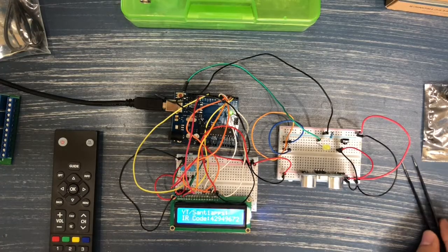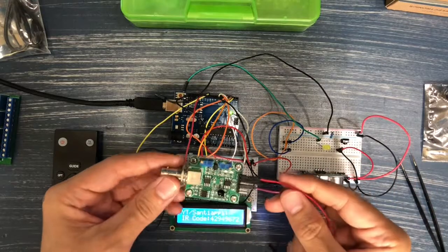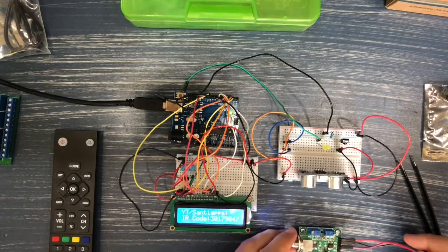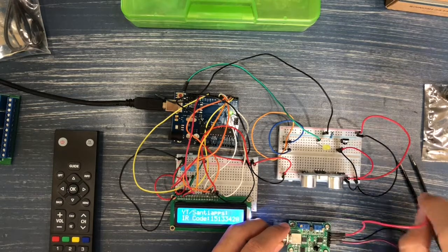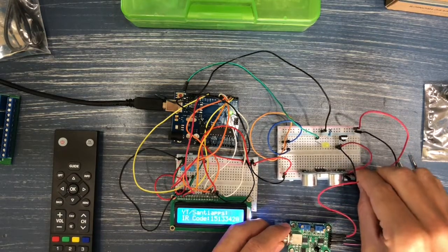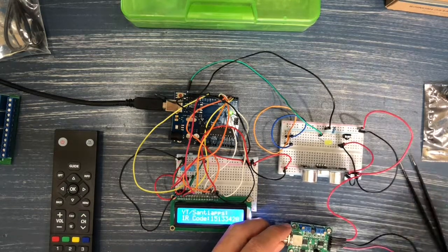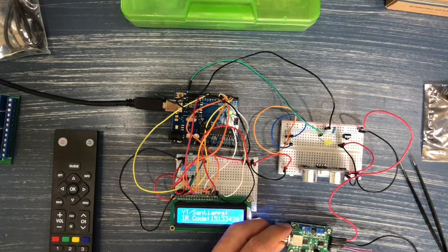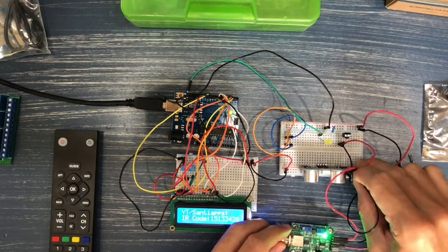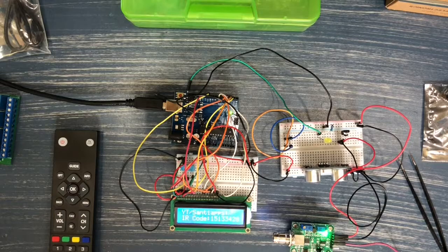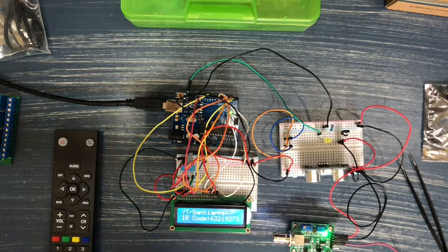Okay, so we are going to look at this pH meter module. This is the circuit board, and as you can see, it has the digital pins on the right side here, and we're going to connect the VCC to the 5 volt and the ground to our ground, and you can see the LED light up on the circuit board for the pH meter.